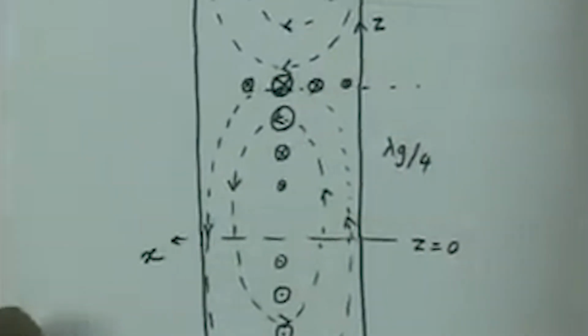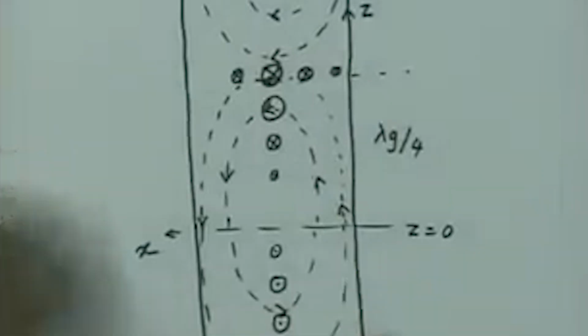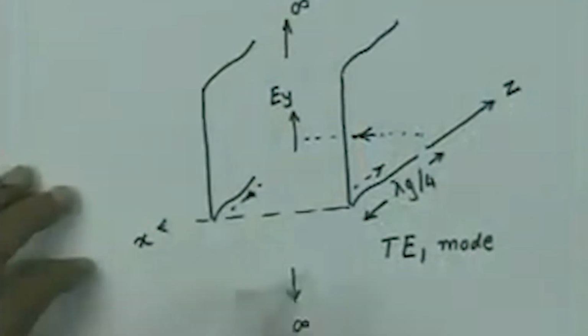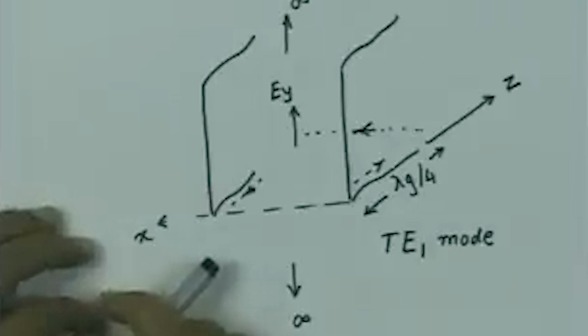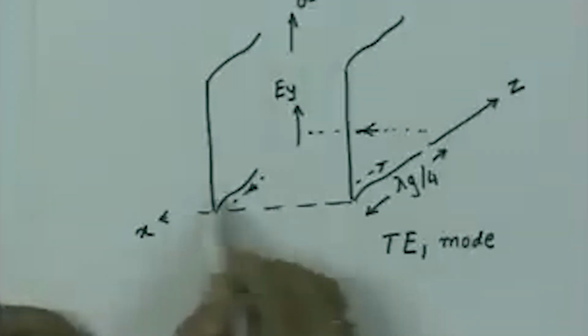Now, we can ask what kind of currents are going to flow in this. So, as we know, the currents will be related to the tangential component of the magnetic field on the walls, and the tangential component of magnetic field on these two walls is only z component. On this wall there is no x component. So, on this wall the unit normal will be going inwards.